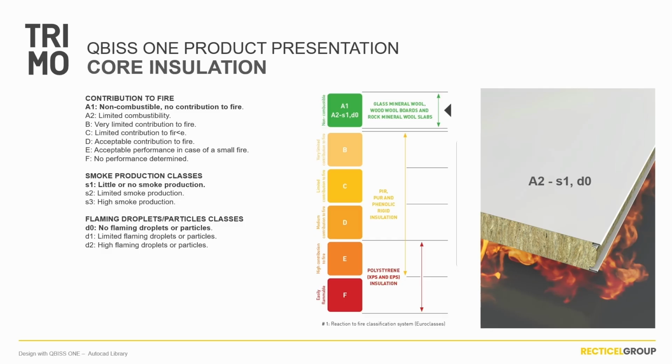Fire-resistant function prevents fire from spreading, and excellent thermal insulation ensures low consumption of energy for heating or cooling of the building. Density of the mineral wool is between 90 and 120 kgs per cubic meter, depending on the required T value, panel span, and fire rating if required.